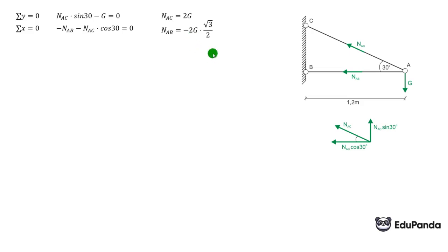with g given as 50 kN. The strength condition indicates that the force in the AC rod is positive, so there will be tension here, just as we were given in the task description. One could suspect that since tensile strength for steel and compressive strength for copper are given, N_AB should be negative and N_AC positive, to indeed have tension here and compression there. Although issues with these tasks can vary, sometimes there are mistakes in the statement, or the professor may incorrectly write something on the board, forgetting to add details. It varies. We must be vigilant.